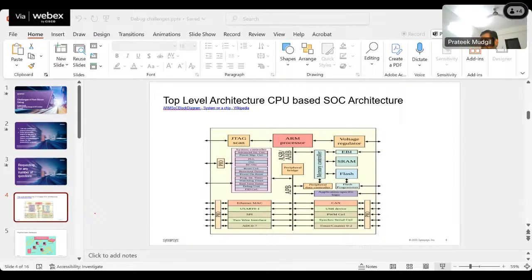So this is timing and impedance, and here is another example. When the silicon comes out and we put it on the board, the first thing the design team does is sit with the silicon testing engineers and make the test setups, do the scan testing, MBIST testing, IOBIST testing, and then go for functional testing to check whether our design is working as per the functional behavior or not.